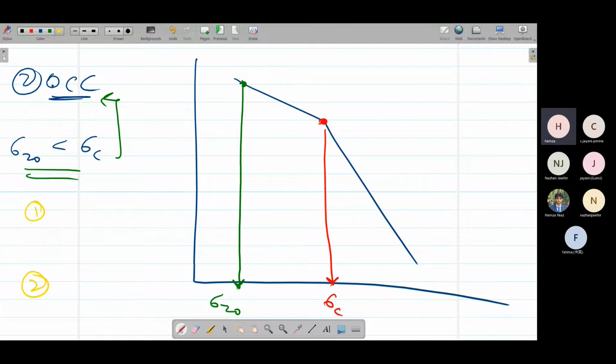After we have applied a load on this layer, for example, we applied a load of delta sigma. So sigma ZF is equal to sigma Z naught plus delta sigma. Sigma Z naught is the initial overburden pressure without any application of load. Delta sigma is the stress from, suppose, a building foundation placed on the soil that increases the stress on the soil. Adding both, we get the final pressure on the soil as sigma ZF.